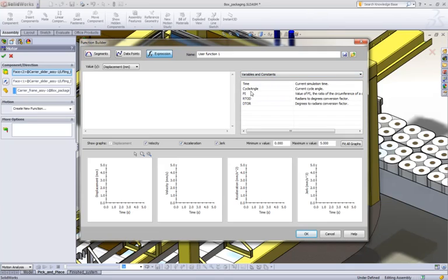Something new in 2011 is support for cycle angles. So if you're in the machine design business and you've got a cycle time for your machine, you can actually set it up and work out everything based on a cycle time, and just adjust the cycle time for everything to scale the timing and movement of the parts. Very powerful tool for machine builders.